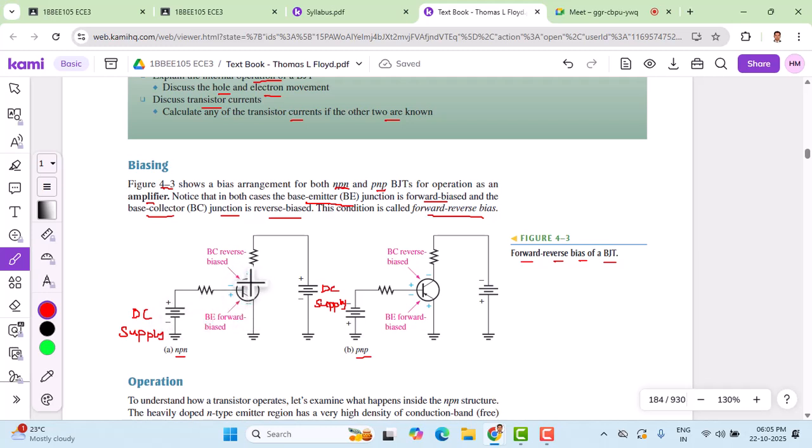First of all, this type of transistor is an NPN transistor, because the arrow mark is outside. You can also see a current limiting resistor used here. Therefore, the collector is N type, the base is P type, and the emitter is N type again. Check the polarity of the power supply connected here. This ground is virtually at different places, so this point is the same as this point.